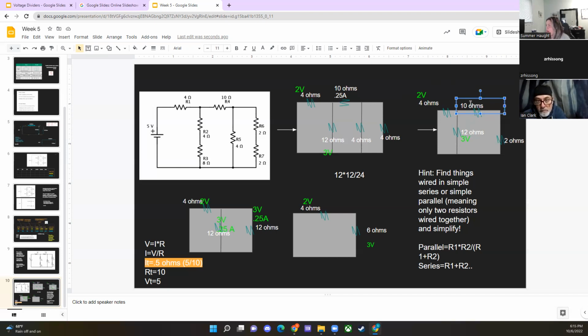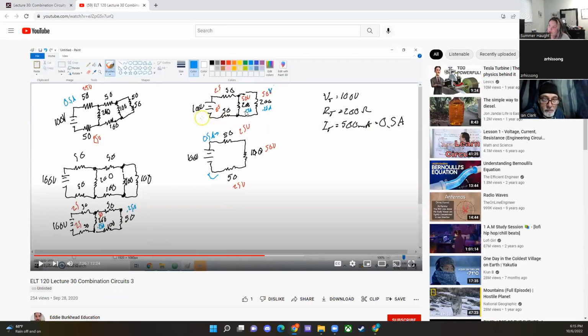So sometimes, even though the questions might say calculate voltage drop, by theory, when you're working through this, you might have to calculate amps first and then go back through and calculate voltage drop. That's probably what can get confusing, but that's just something to keep in mind. And that's why in the videos, looking at this at large, he's writing in these amperages as he's going, because they're allowing him to determine other values later on.